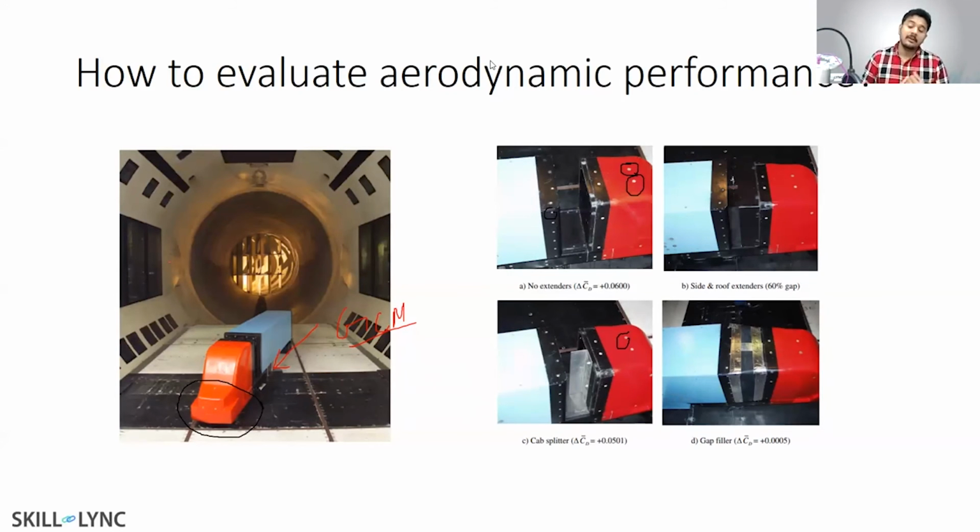Why? Usually, if you have an underbody, you will need to use advanced cleanup tools to clean the model. And when you do that, you slightly deform the truck, right? Because of that, your CFD results are going to change. So what people did at NASA is they made the model so simple that pretty much any CFD solver out there would create an almost identical mesh.